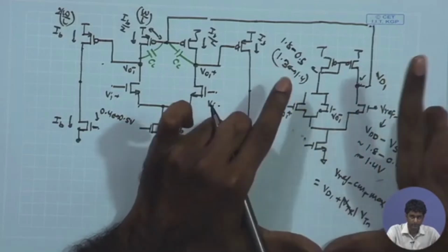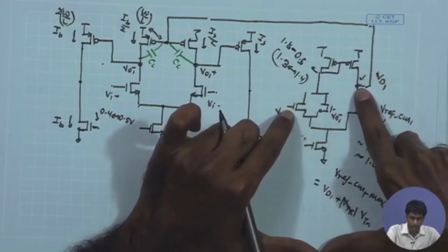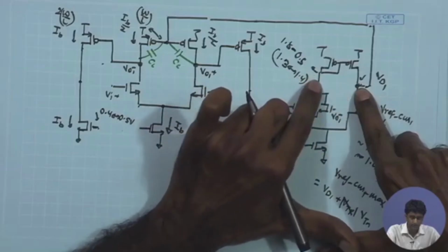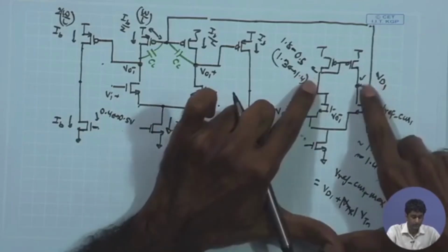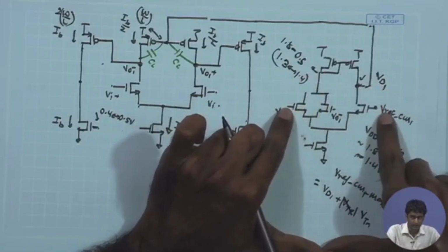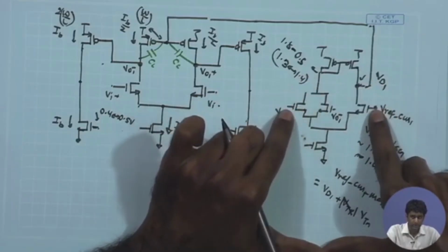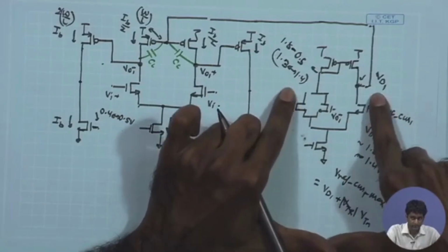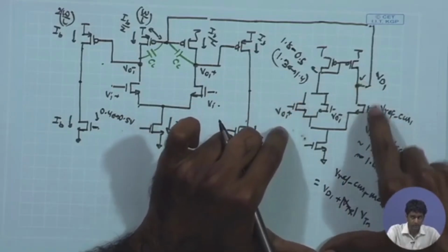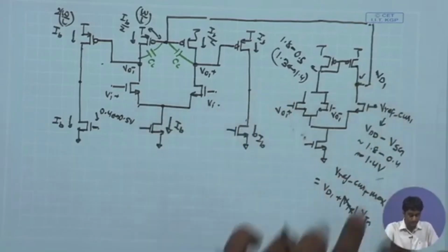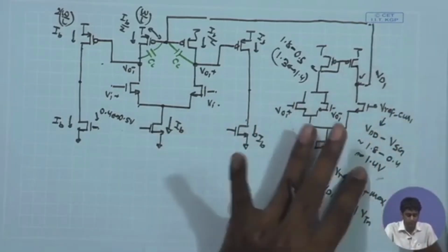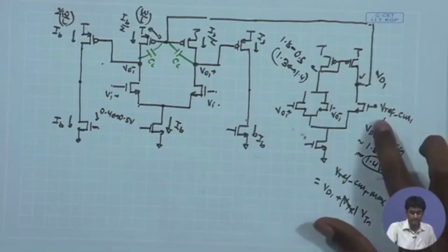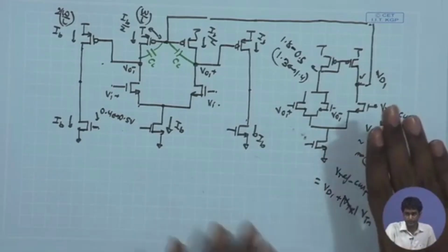So, that is why we are first of all finding out the Vd1, which is going to be close to the DC potential over here, as long as these two potentials are close, and then for that Vd1, what is the maximum VCM ref that you can have, that is going to be equal to Vd1 plus Vt. So, that is going to be pretty large, it can go very close to Vdd. So, 1.4 is not an issue as a VCM ref.